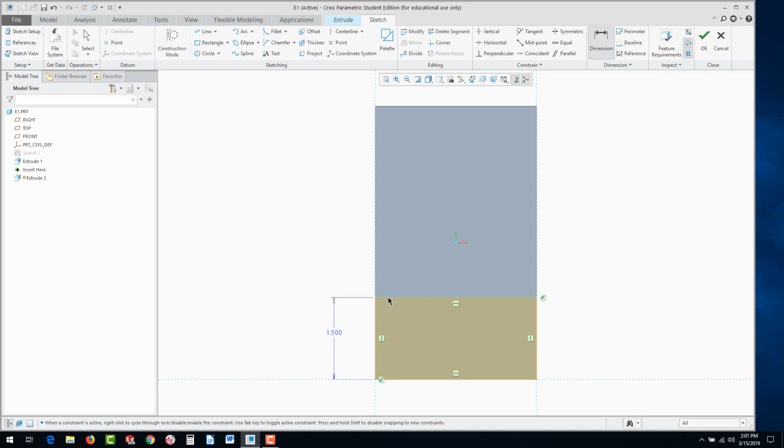And then we would be able to have this line go out of sync from horizontal, and it could go at an angle. We could put a dimension then on the right side that would control the length, or we could put an angle dimension in, which we'll learn in upcoming lessons. Anyhow, let's go ahead now. We're going to hit OK. And one reason we didn't need this one dimension for width is because it's tied in from this corner to this corner, and it has vertical relationships, so it can't move.